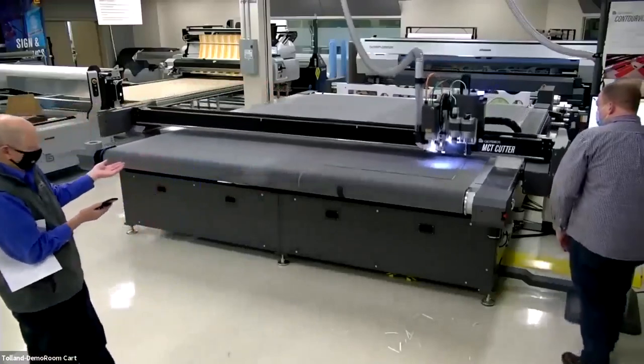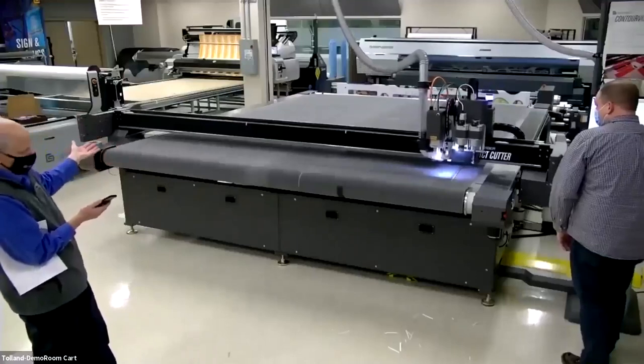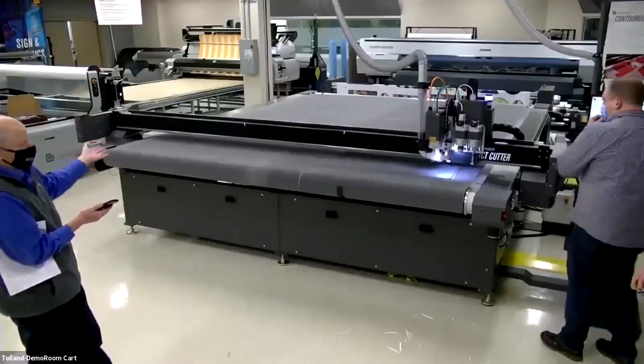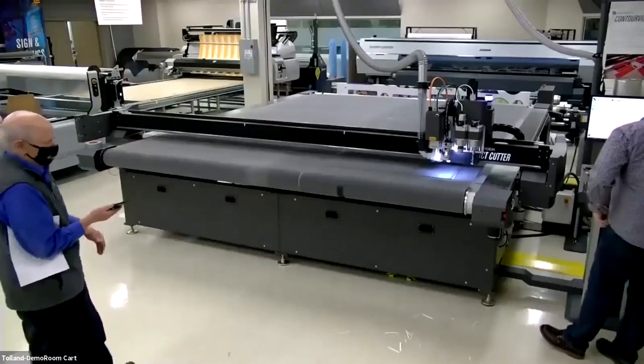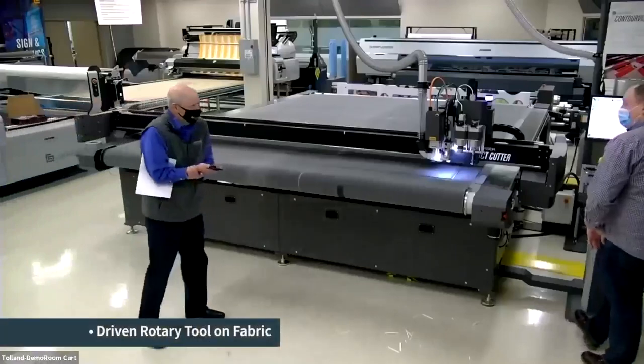You can use the DRT together with the laser, which is a great combination. Someone asked a question about the laser earlier: if you have PVC in a material, you don't want to laser cut it. Chances are very high you can probably cut that same material with the driven rotary tool and get very good results.